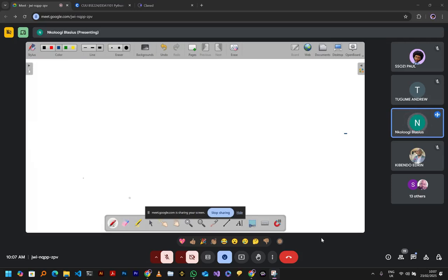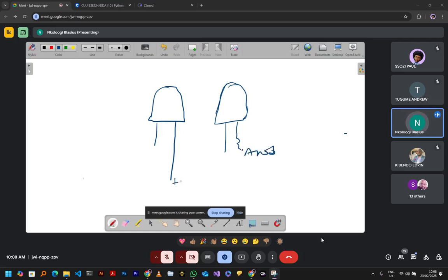In some books and on the physical looking of these LEDs, you will have an LED look like this, just long like that. But on Tinkercad and maybe other simulation software, you will see something like this, just something not straight. This means that this is the anode, which is the positive. Anode here. So connect accordingly, please.